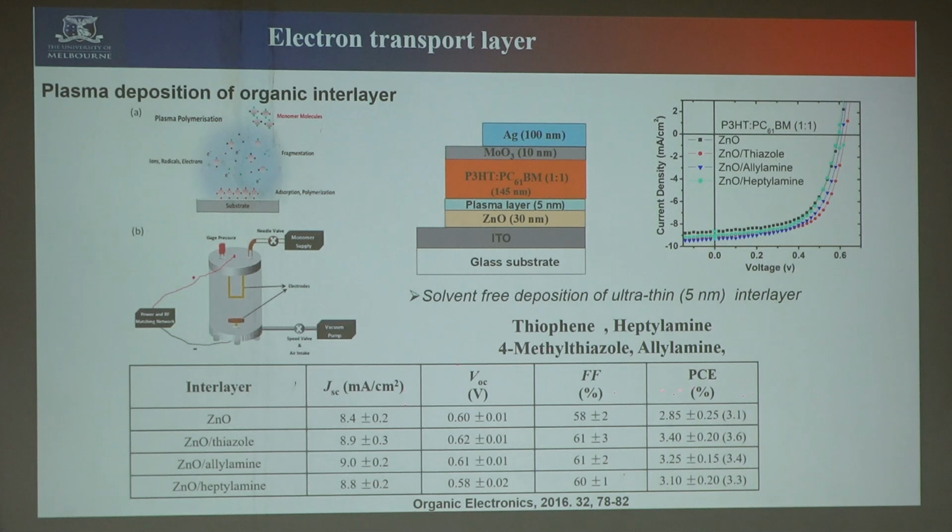And another option is how to get another one we have tried, which is plasma deposition, because so far all the things we coated were spin coating layers. To reduce the contamination effect, what we did is generate the plasma, inject the material into the plasma chamber, then coat it on the substrate, and we studied the device performance on top of zinc oxide.